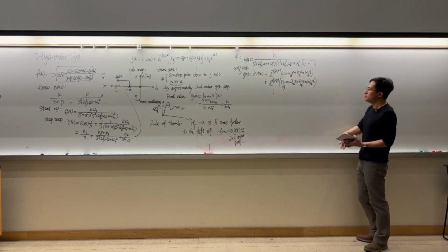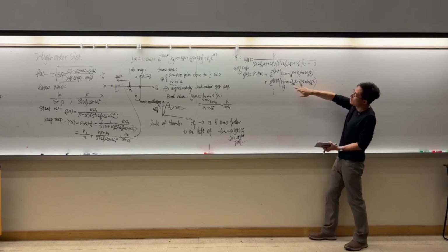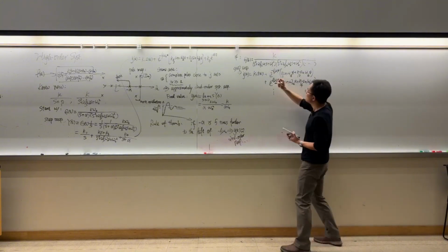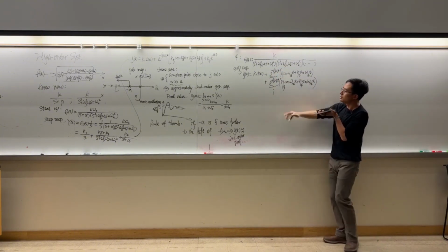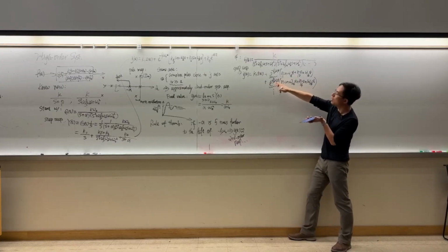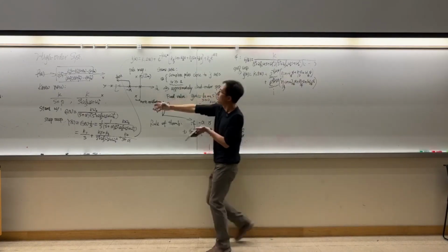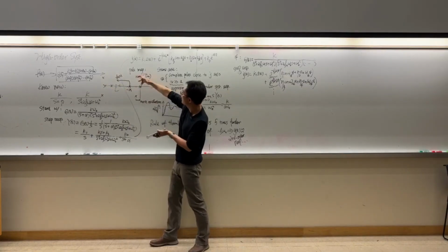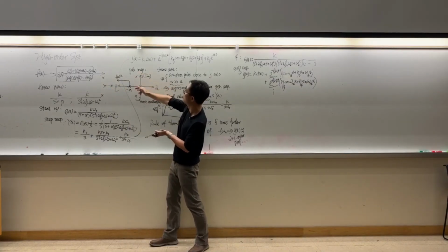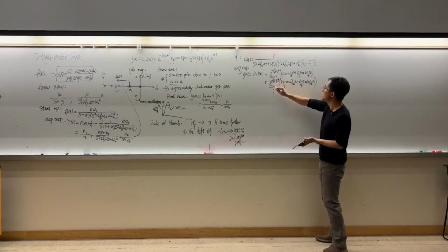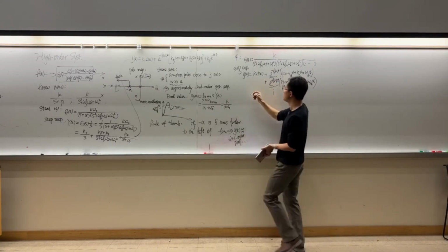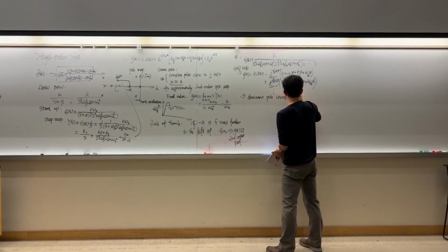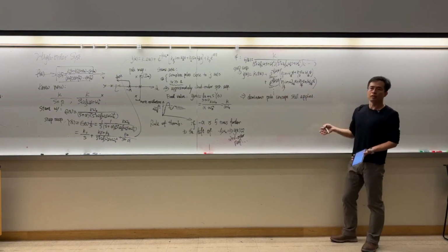All right, so there will be more complex oscillations in these individual modes, but there will always be exponential decay components. And if zeta 2 omega 2 is very, very far away from the first dominant pole, then you can see this part will decay very quickly. So the dominant pole concept still applies, and the rule of thumb also applies.